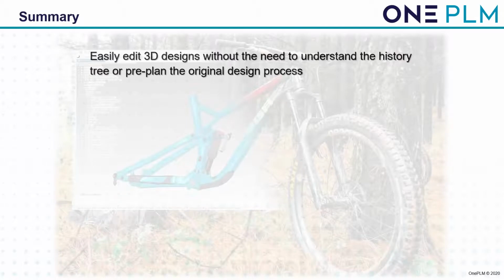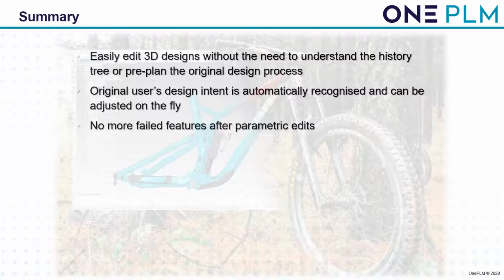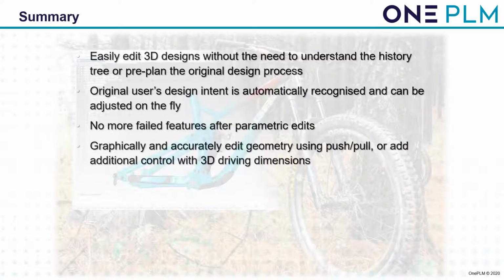Okay, so let's do a summary. Solid Edge Synchronous Technology allows us to easily edit 3D designs without the need to understand the history tree or pre-plan the original design process. The original user's design intent is automatically recognized and can be adjusted on the fly. There's no more failed features after parametric edits, especially something early on that tree. Changing that first option can cause anything to go wrong down on that tree.